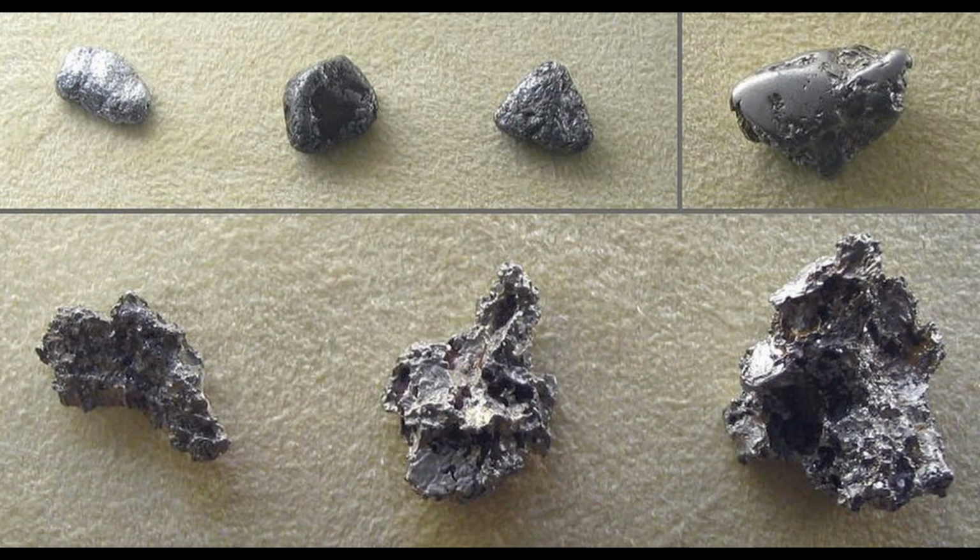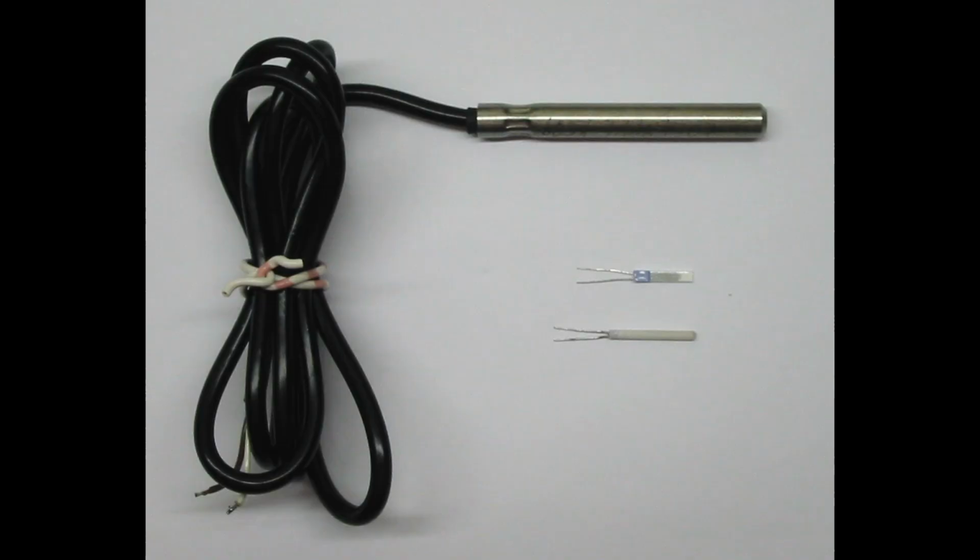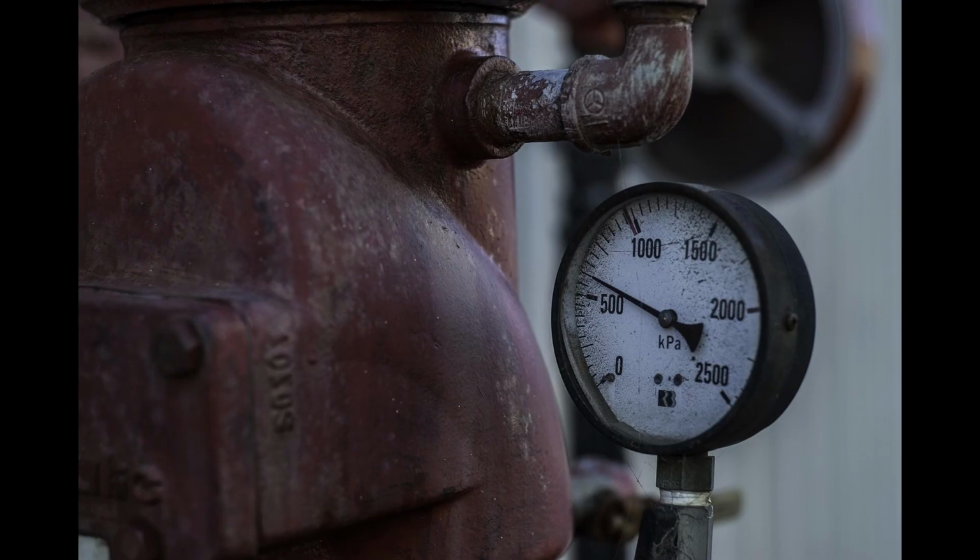Another kind of temperature sensor is a resistance temperature detector, or RTD. The electrical resistance of a material changes depending on its temperature. Certain metals, like platinum, have a linear relationship between their temperature and resistance. As such, there is a consistent, predictable output within a range of temperatures. The sensing element is usually in the form of a wound coil that is housed in metal or glass with the leads exposed.